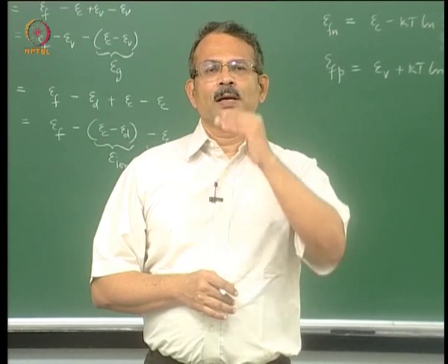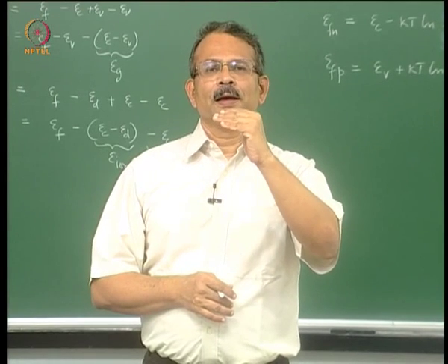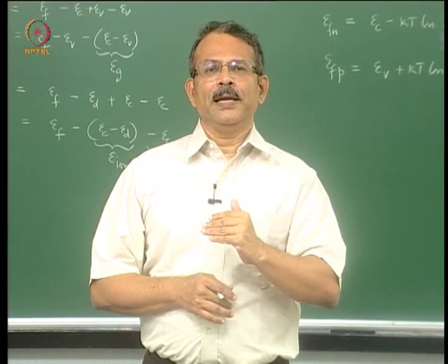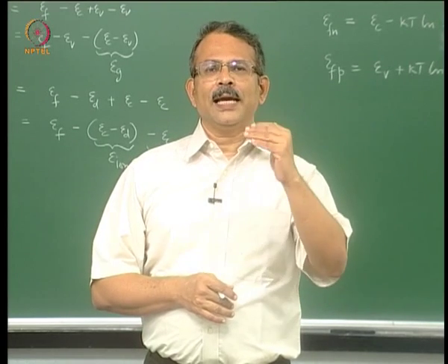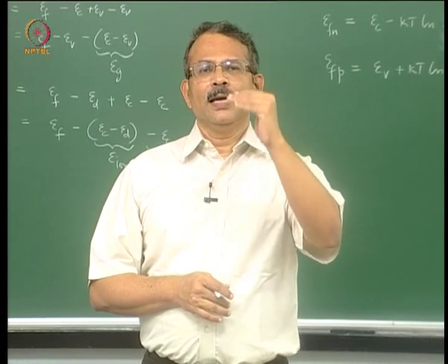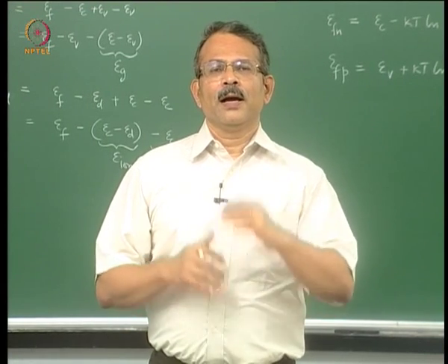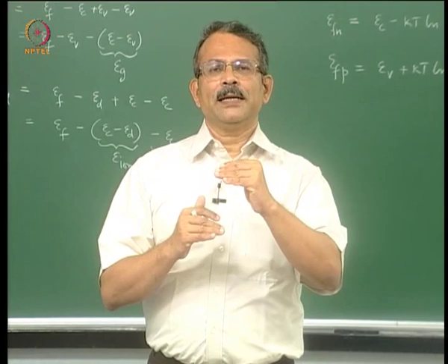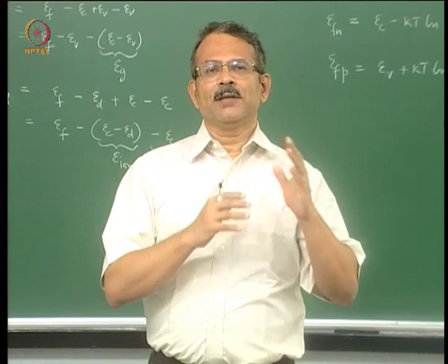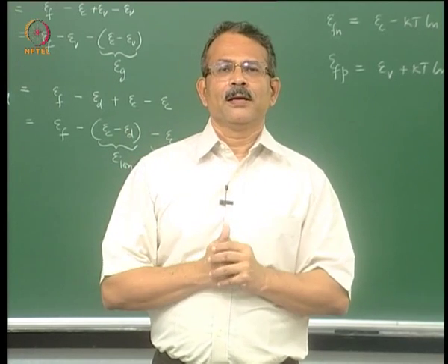This is how the levels E naught, EFN and EFP together represent psi, n and p, or E, Jn and Jp of the drift diffusion model. EC and EV represent the variation of the E-k relation throughout the semiconductor volume.